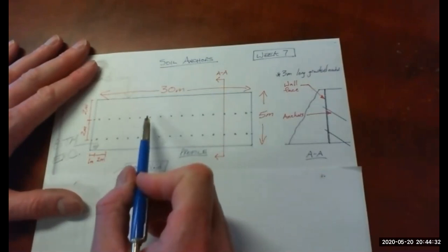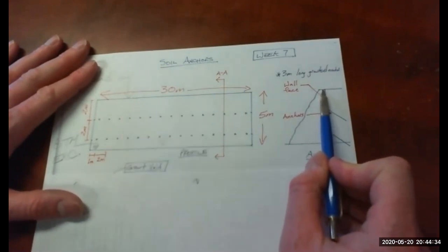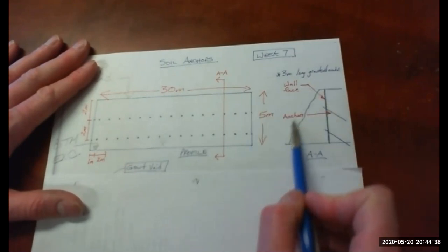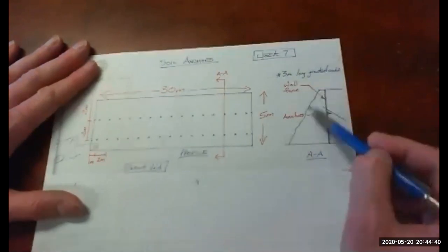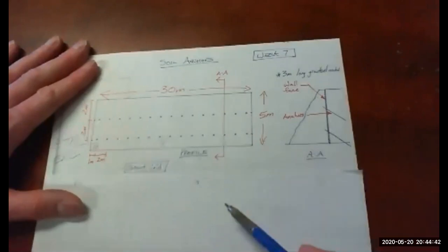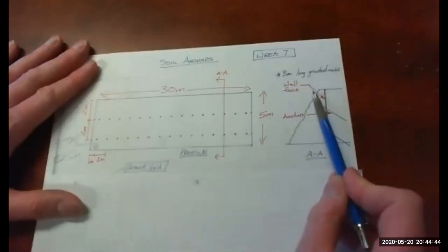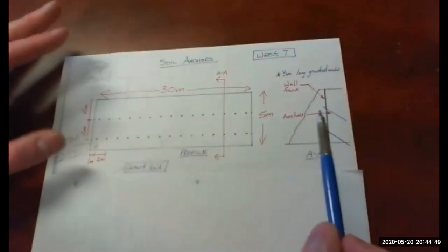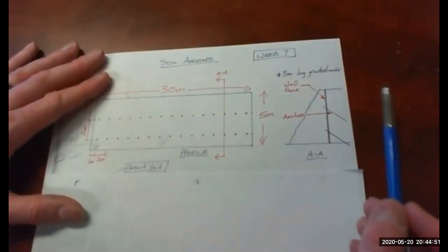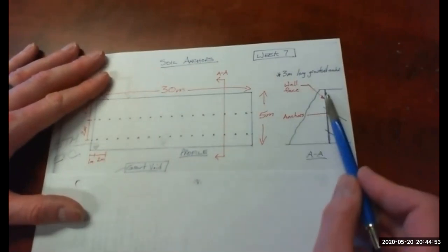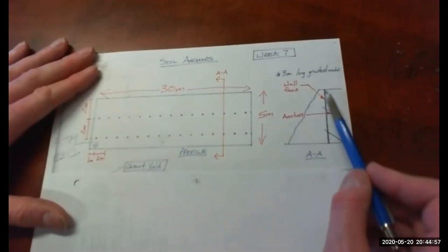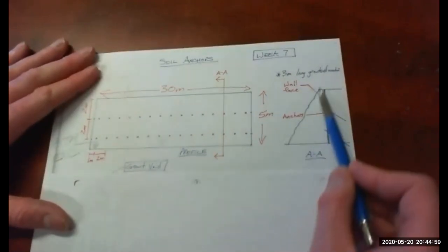If you were to start this excavation, you could do the bulk excavation. All of this material here, you could dig out. This could be your temporary cut slope here. So all of that could be dug out, and you've left this wedge. I haven't dimensioned it because it doesn't really matter what it is. Maybe it's 1-to-1, maybe it's steeper than that, maybe it's 3/4 to 1. So you've left this wedge of material in there.